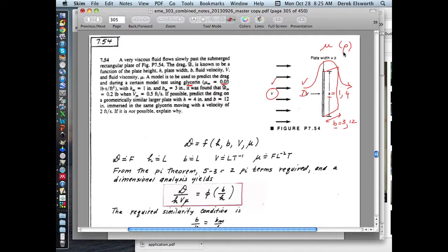When we talk about external flows, we'll realize that you can get drag and lift. So lift is the force which is perpendicular to the flow direction. Drag is the force that's in the same direction as flow, as you can imagine. And they come from two sources. One, you could imagine if you have a very viscous fluid flowing past something, there's a big drag on it, and it's the viscosity that's causing that drag.